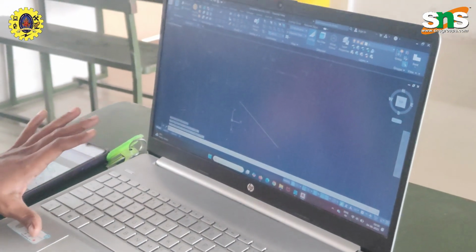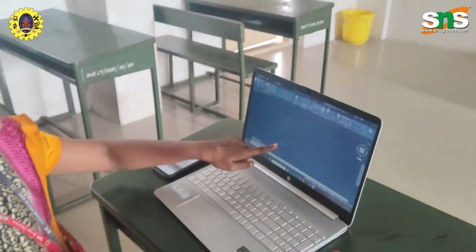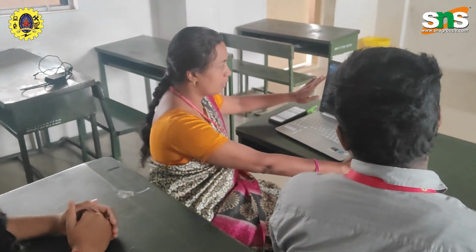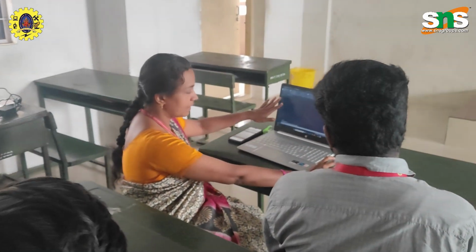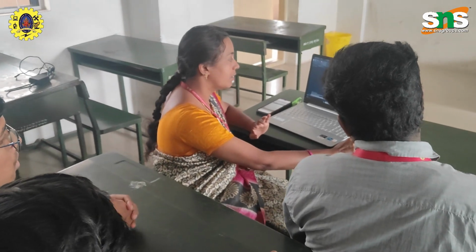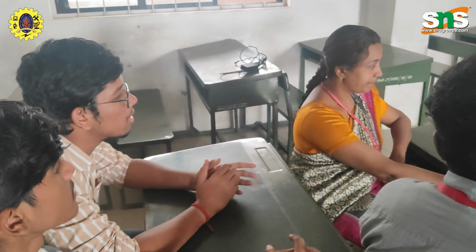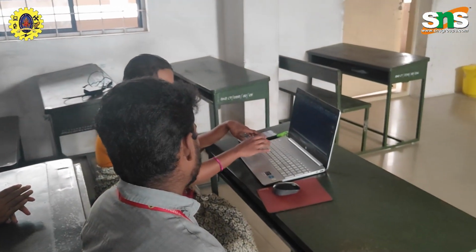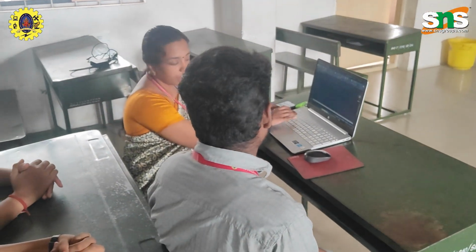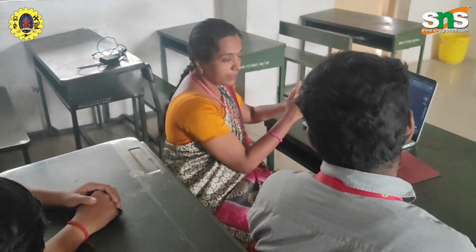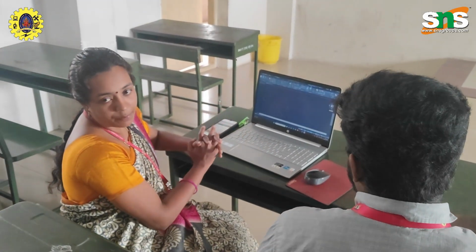Now this axis plane is here. Let me keep it in the corner of the workspace. Anything you want to ask till now? How to change the axis plane? The key option is Control E. You can use Control E to change from isometric left to isometric right and isometric top.